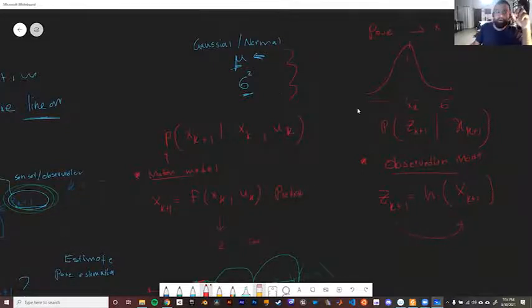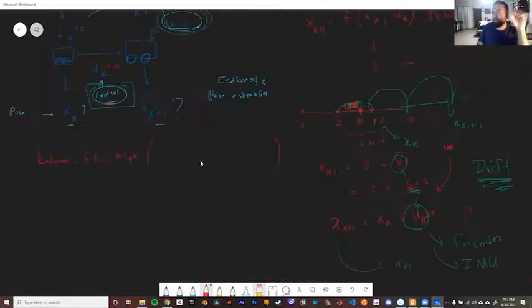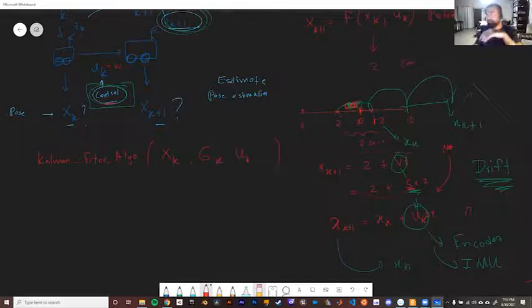So into the algorithm, what's going to go in is simply xk, that is the previous step. Remember, this is recursive. Xk, and then we are also going to include sigma k, the variance of the system. Then what else is going to get input is our control signal uk. Along with it, the other thing we are going to input is our observation, zk.